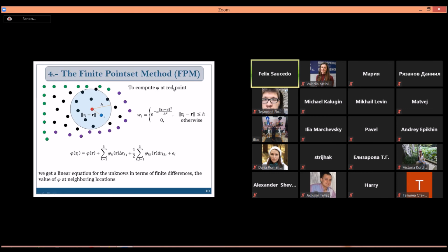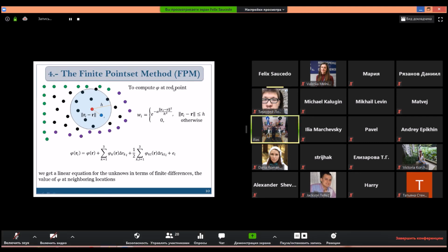So we can put mesh-based methods in for problems where you have no high deformations or fragmentations or this kind of issues, and you can put meshfree methods, my method, finite pointset methods, in the category of high deformations, fragmentations, sprayings, atomizations. So this will be the idea, for example, of how to decide between these two families of methods. Thank you. You're welcome.